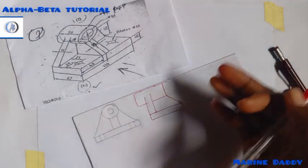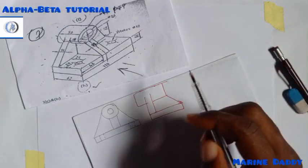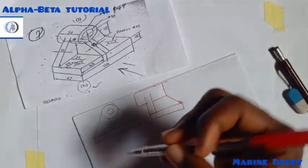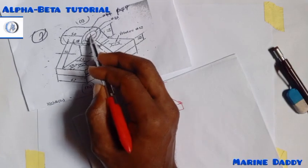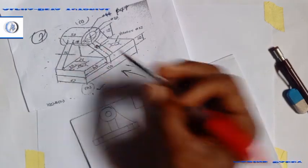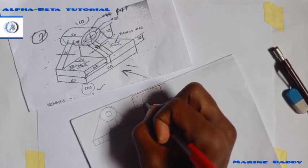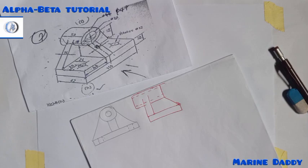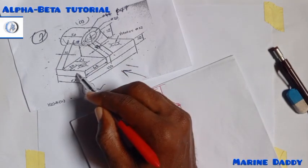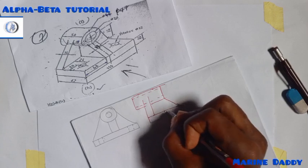Please, this is a sketched work, so it's not going to be as accurate as when you use dimensions, but it's very good you start with a sketch so you can easily tell how it's going to look. The hidden details, that's this hollow part, we will not see it from this side, so I'll indicate using a broken line. Now this part of the diagram too will be hidden from here, so I'll use a broken line to indicate it.